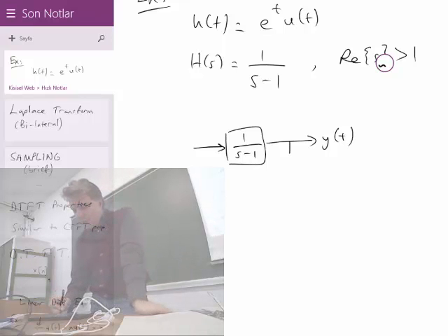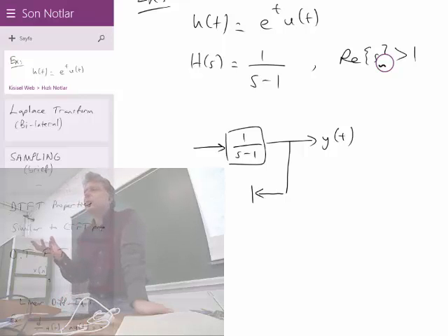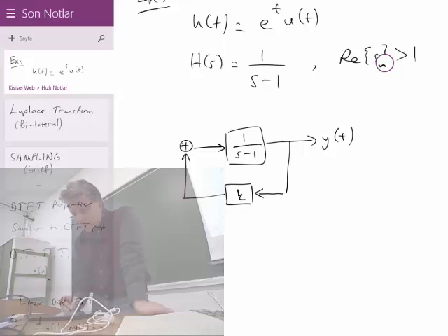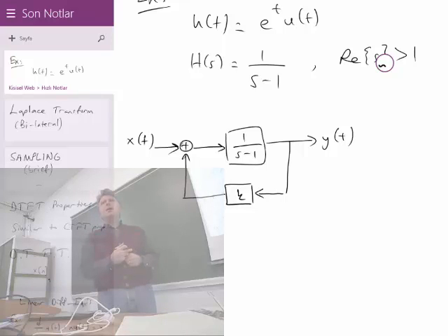And the popular way to stabilize this one or such systems is called a feedback. Okay, you may know the name already, a feedback. Now I'm going to use a feedback, and a simple feedback. So the input comes from here. The simple feedback is just a scalar. It multiplies the output signal with k, and it feeds it back to the input by combining with x. So under which values of k, or what region of k, can we make this thing stable?